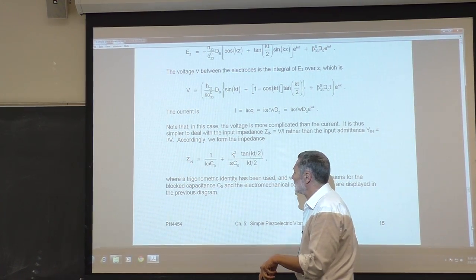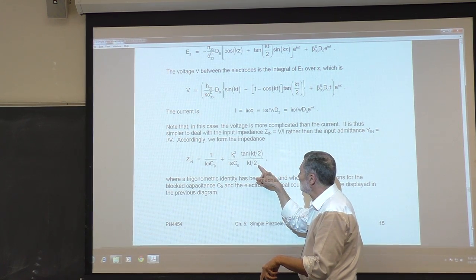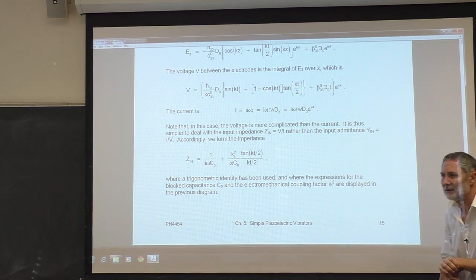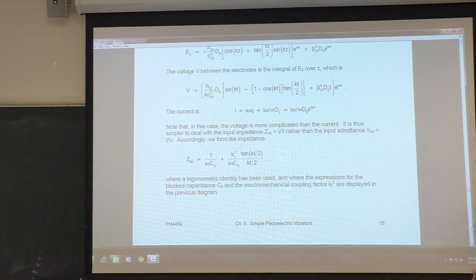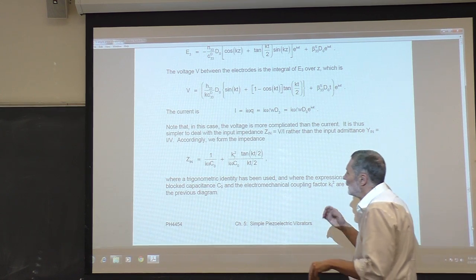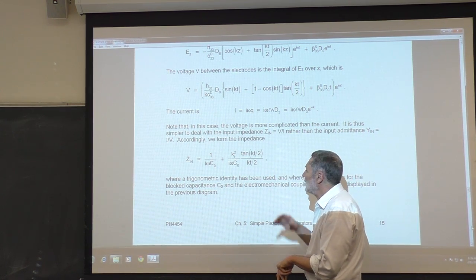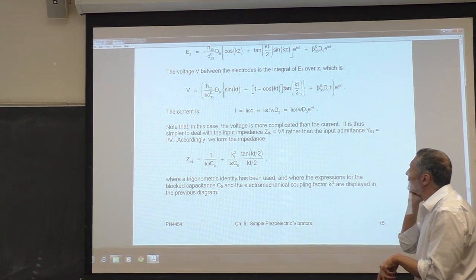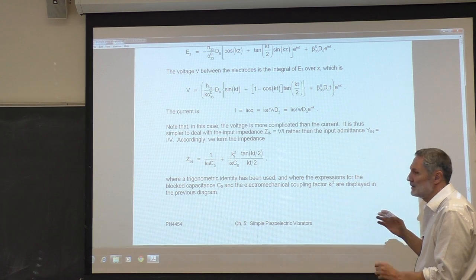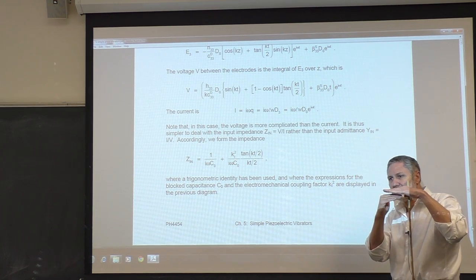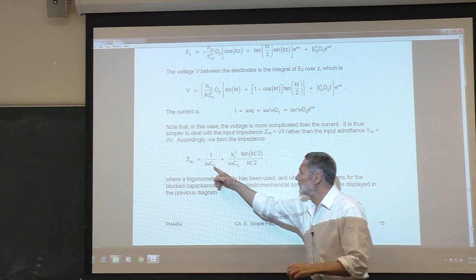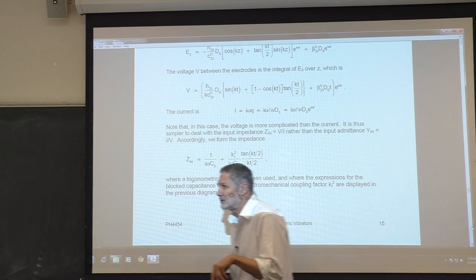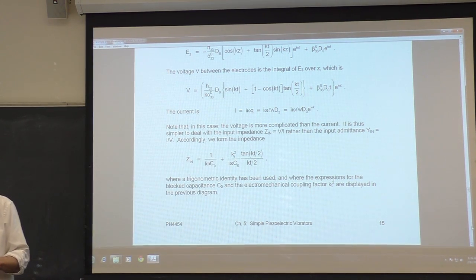I don't know if that's such a great reason, but you'll notice it's got the standing wave character in there, which is a mechanical thing. When we block the system, when we block those upper and lower plates there, this is what you're going to see. You're going to see a capacitance, and it's C naught, the blocked capacitance, which is also, of course, listed just below the circuit.